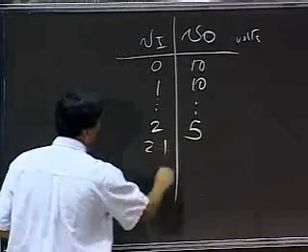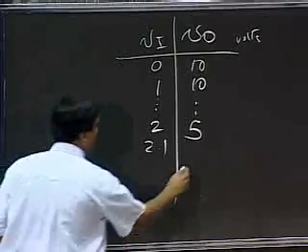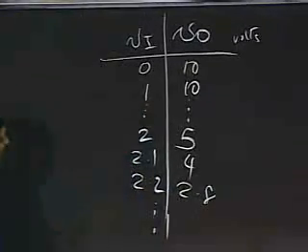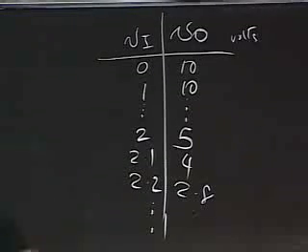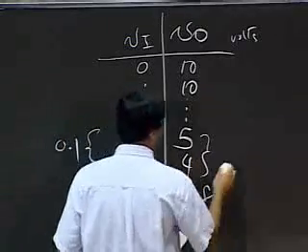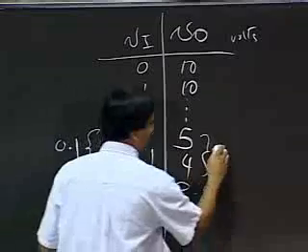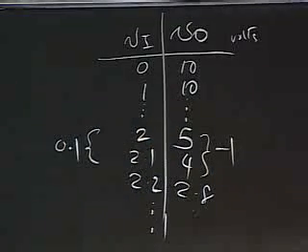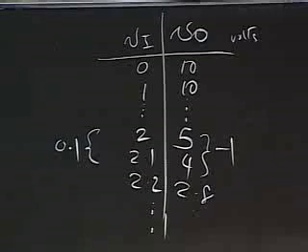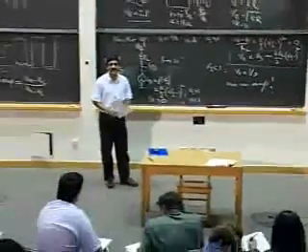And then you can go and do the math. If it's 2.1, I get 4 volts here. 2.2, I get 2.8, and so on. Notice that when I go up a 0.1 volt change this way, it results in a minus 1 volt change there. So input went up by 0.1 volts. My output kerplunked down by 1 whole volt. So a small change here resulted in a bigger change there, and that's the amplification that I am claiming here. Okay, so let me show you a little demo of a small device that I built involving such a dependent source.